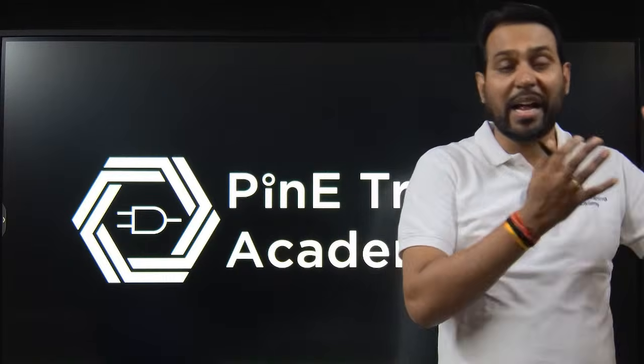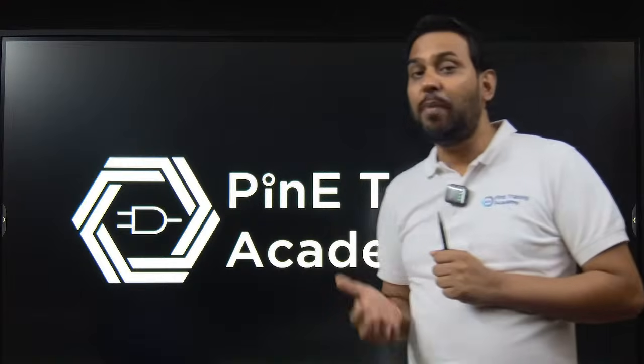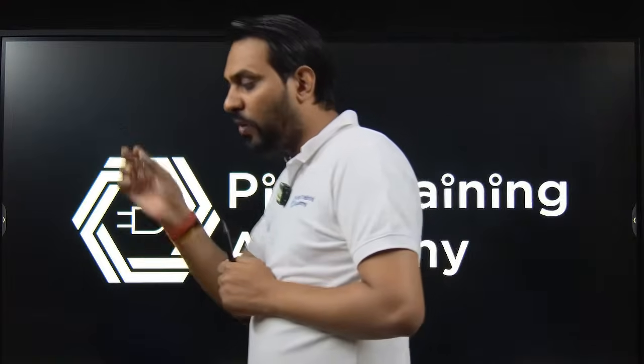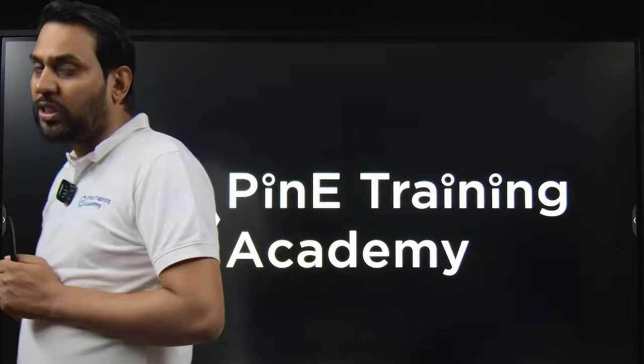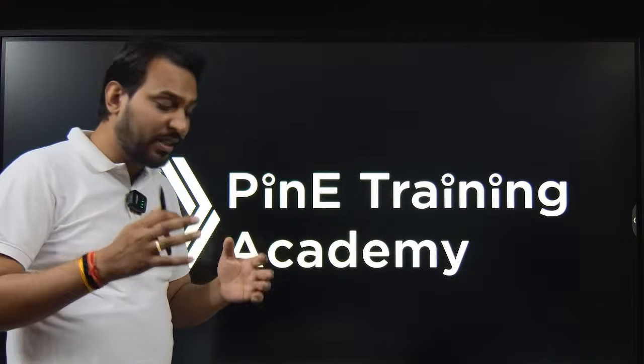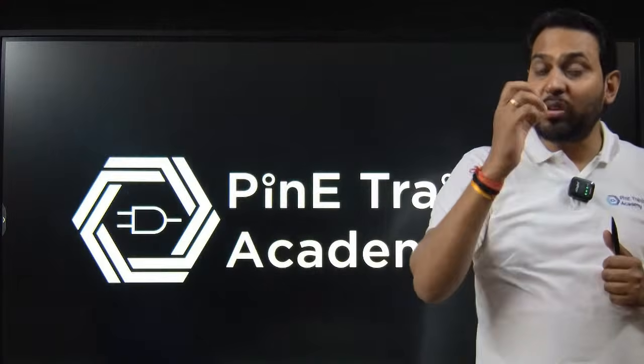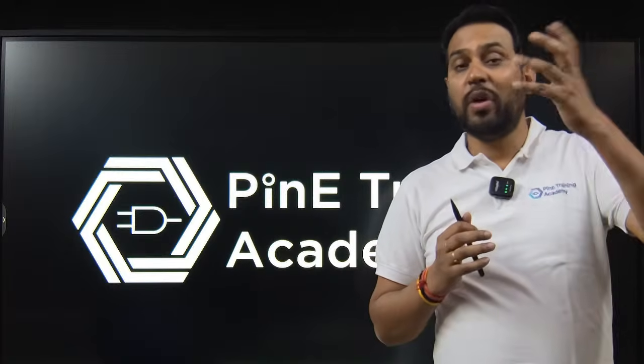A MOSFET acts like a resistor. A MOSFET behaves like a capacitor also. You can design a MOSFET with the source, drain and body shorted to become one terminal, and the gate as a different terminal. So a voltage controlled capacitor is also present, and you can store the electric field as you would with a capacitor.